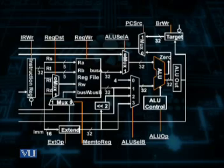So over here you can see that if the condition is satisfied, then ALU select A is made equal to 0, and ALU select B is made equal to 1, 0, where with the help of this 1, 0, we pass on the value of the immediate sign extended with shift to the left. The signal branch write, that is BRWR, is asserted, and the program counter source of the multiplexer 2 is made equal to 1 to pass the target address to the program counter, which is shown here.